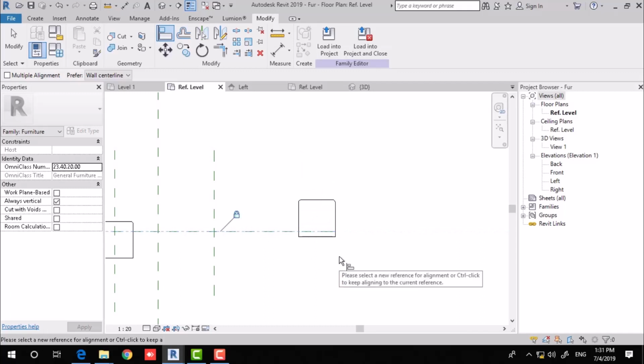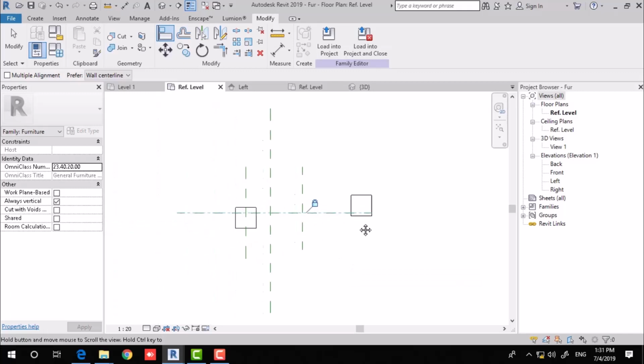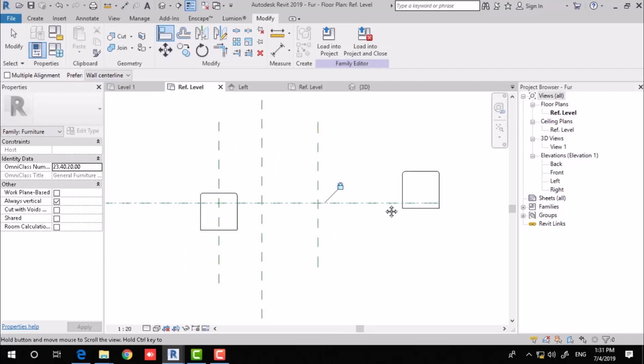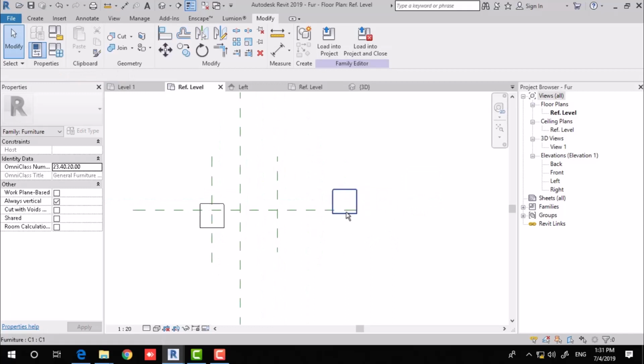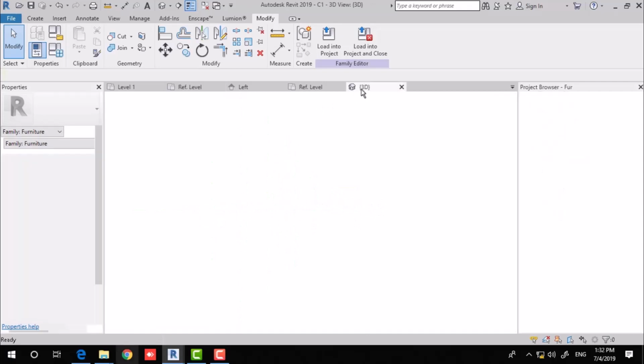By this way, you can align your object. As you can see, it is aligned with the reference plane. However, it is not at the center of the lines. So we measure the aligned distance and then sketch the reference plane. The reference planes allow us alignment positions for our model geometry. This is a very important lesson that later I'm gonna deal with more.